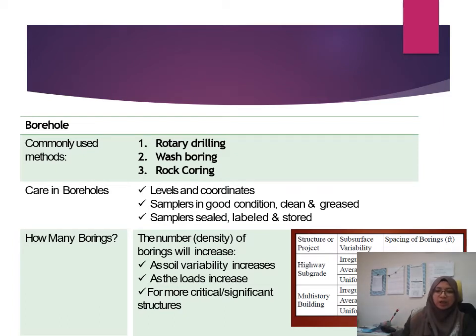Number 2, as the load increases, right? Just for simple differentiation, for example, you have a single-story building and multi-story building. So of course, for multi-story building, you have to conduct more borehole, right? So as the load increases, you have to increase the number of borehole, right?